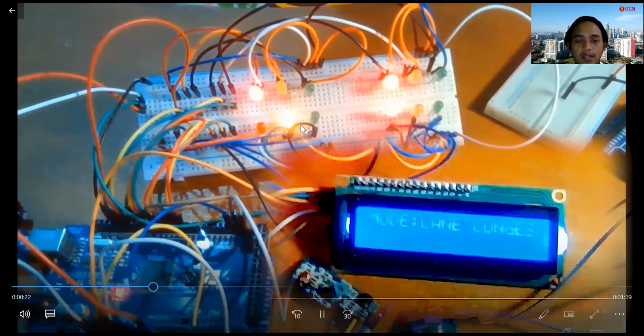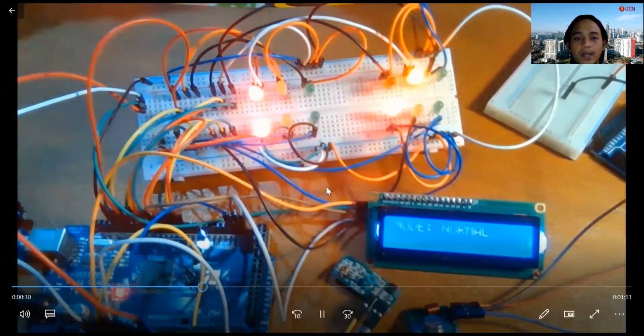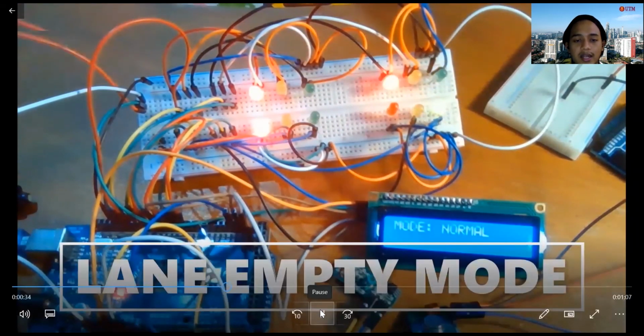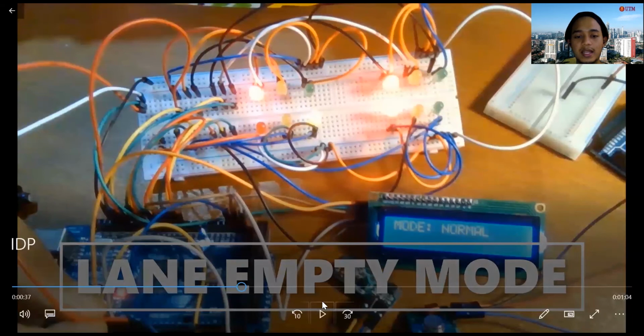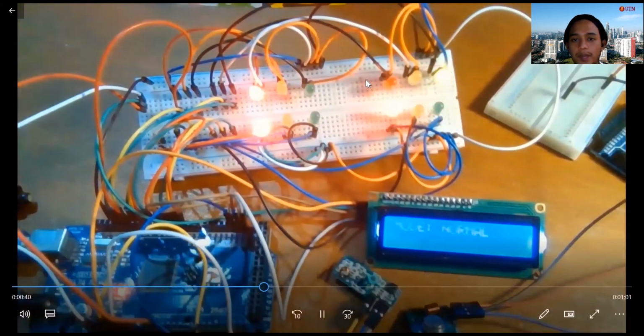And when it comes to this lane, it will be longer and it's in the lane congested mode, meaning that this green light will be turned on longer to let other cars pass through longer than the other lane. So in the lane empty mode, I triggered another pin that said that this lane is empty, meaning that no car is on the lane currently. So when I trigger that switch, this green light will be shorter compared to others.